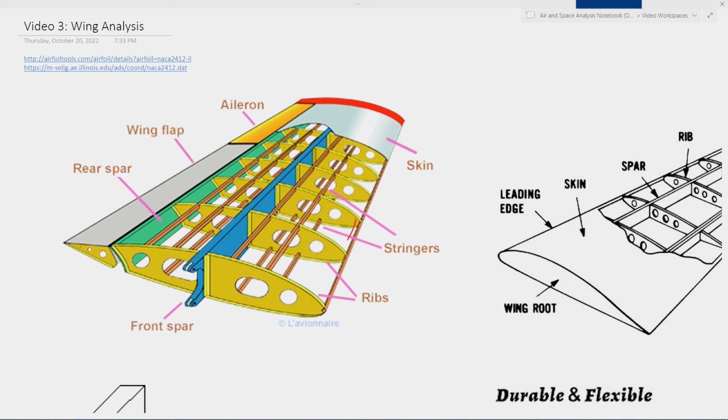So essentially, we have here our main structural elements called spars. That is this big blue beam that runs the entire length of the wing. And we have a front spar and we have a rear spar, this green one back here. These two spars are our sideways rulers, right? These are nice tall beams that are pretty difficult to bend along in the direction that we're going to be bending. So these blue beams run the whole length of the wing, and this is our tall ruler that's very hard to bend. So that's the rear spar, this green guy, and the front spar, this blue guy.